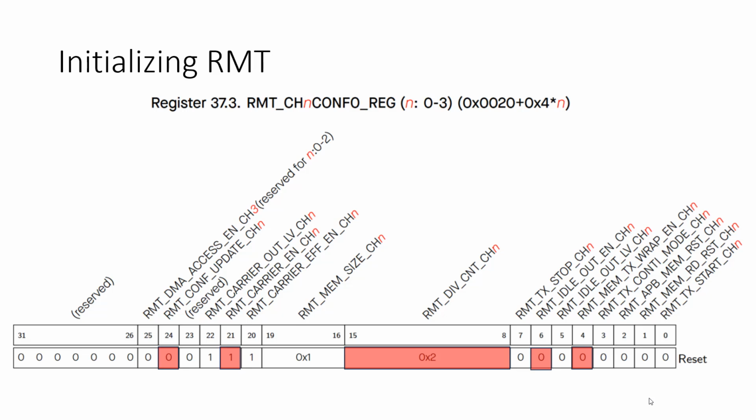And again, you can see the address there. That's an offset. There's actually, the N is part of the offset too, because there's a separate one of these registers for each of the 8 channels, right? So in order to calculate the address of this, you have to multiply by the channel number, or in this case it was 0, so it's not a big deal for us. Okay, so there's a few fields in here you want to change.